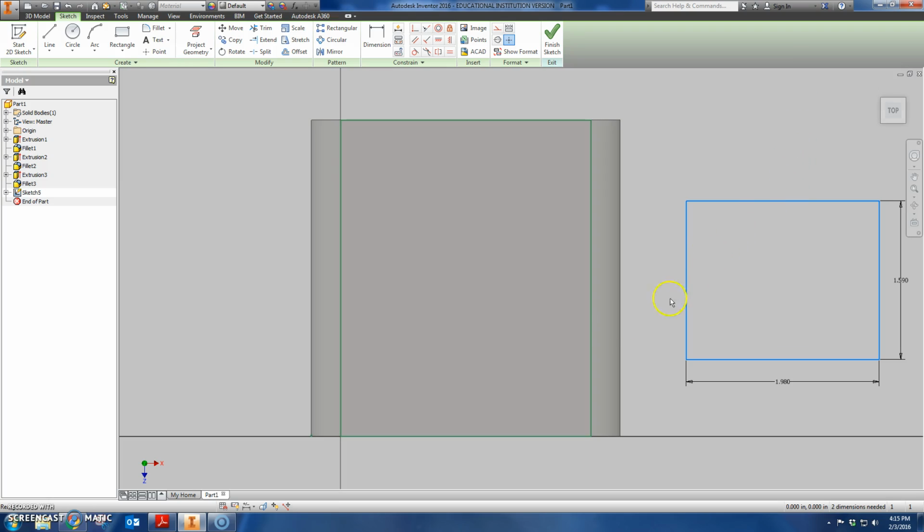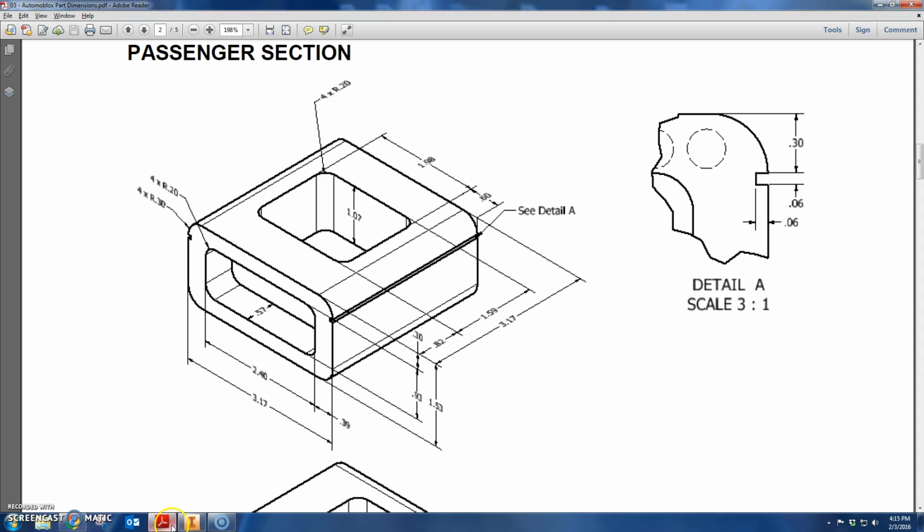So here's what I know about this rectangle. Okay, if I look at this drawing left to right, I notice that this is centered. Okay, now be careful about this. You see a 0.60 here, right? Understand that that is a rounded dimension. It's rounded to 2 decimals, when actually it's a 3 decimal number. We really want this to be centered left to right. So if I look at this and consider this to be the left side over here, and I consider this to be the right side of the shape, I need it to be centered halfway between those.